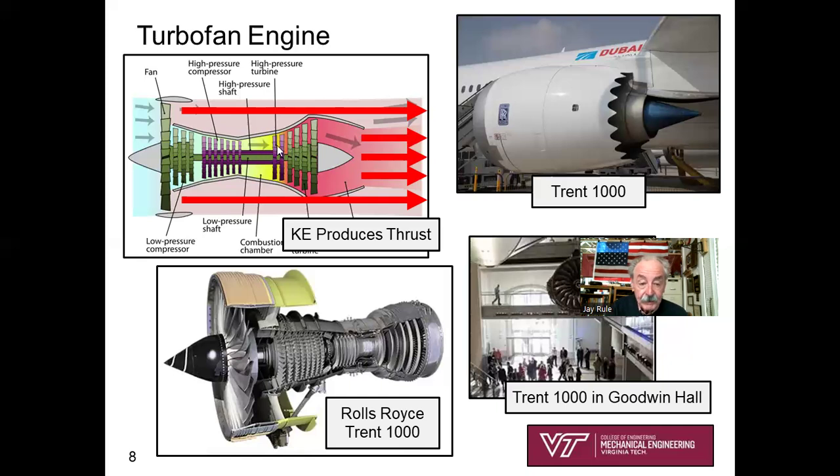But then also you have a turbine section that's driving the compressor in order to get you high pressure air into the combustion chamber. And so this is the traditional Brayton cycle model. So it's a turbofan. You see, it's a combination of engineering components that's providing thrust, and of course, ultimately, the idea is to provide thrust to the aircraft. And so it's the combination of this fan plus the kinetic energy of the outlet of the gas turbine engine.